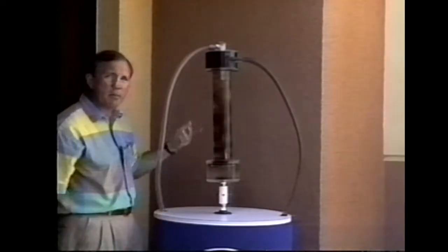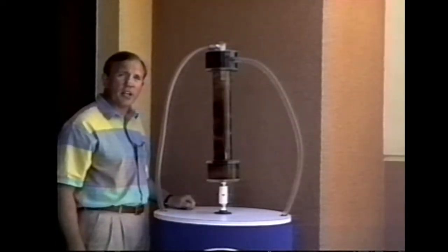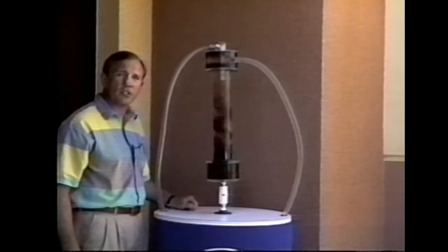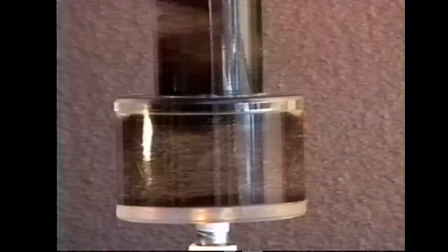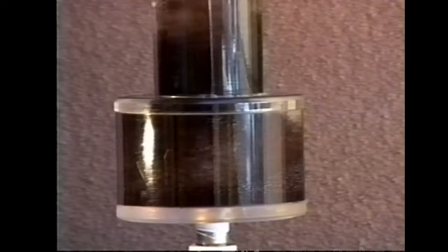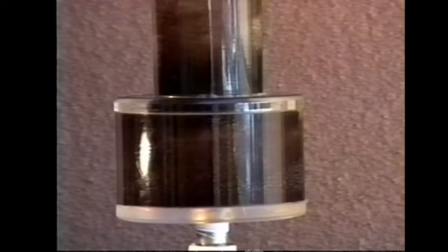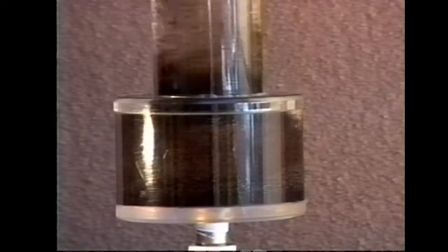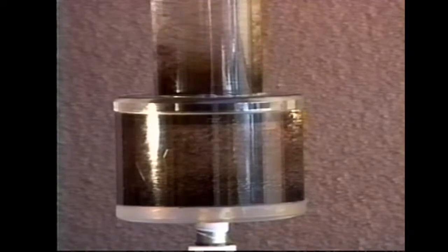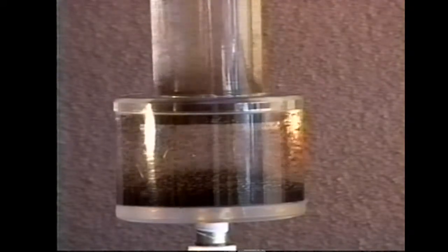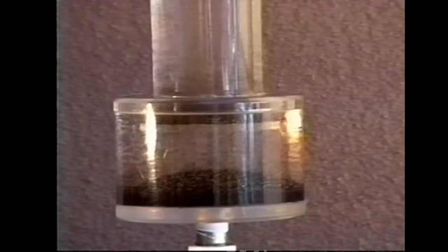Now, of course, it's coming back into the demonstration unit here. Normally, this would flush out to a waste site or to some other area for disposal. As the particles are separated, they fall off of a spin plate located in the collection chamber. That spin plate not only allows for the quiet accumulation of the particles, but also provides a place for the vortexing water to turn and discharge out the top of the separator.